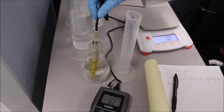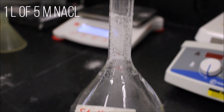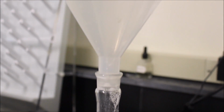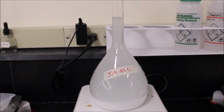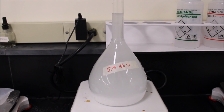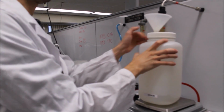The first step is to calibrate the conductivity probe using several concentrations of salt water. Then, prepare 1 liter of 5 molar sodium chloride stock solution using a stir plate to mix well. While the solution is mixing, turn on the chiller, making sure the water level is adequate. Next, fill the draw and feed tanks, each with 2 liters of deionized water.